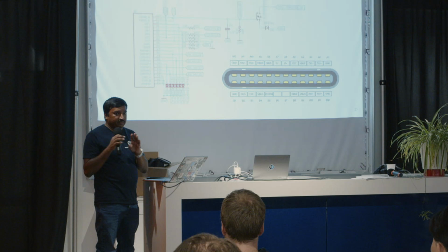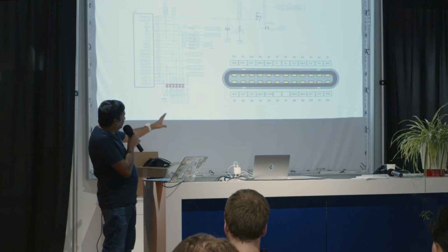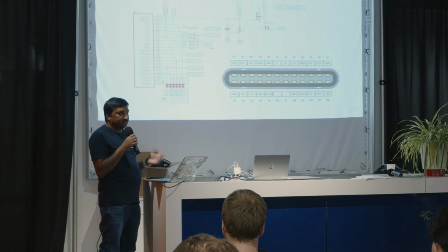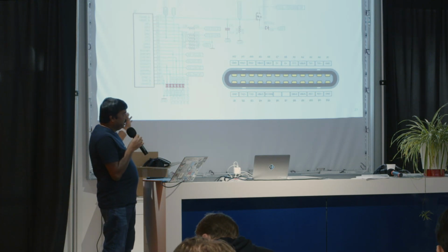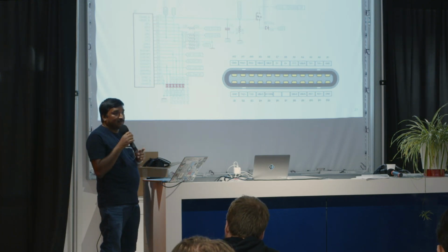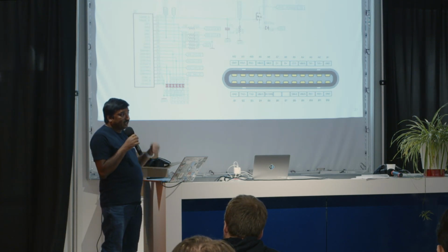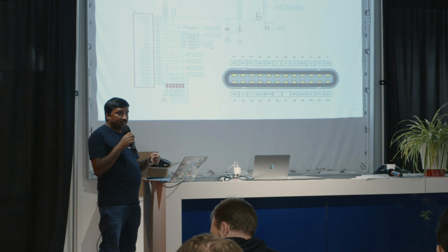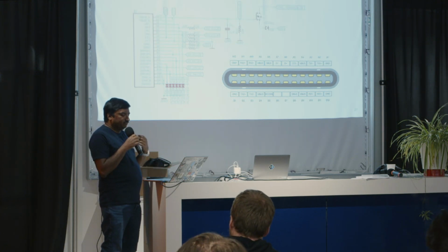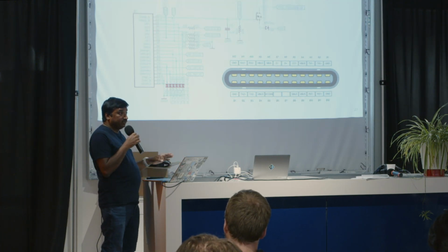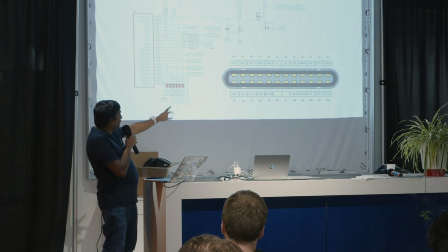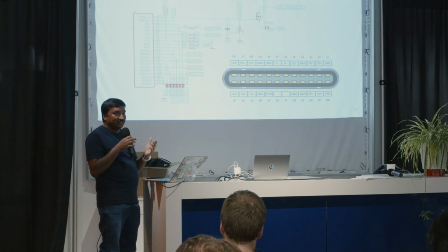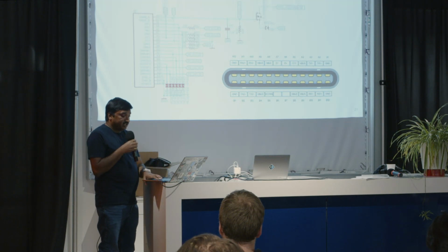But ours still works. The reason it still works is because USB has a hidden mode called debug accessory mode, and we did not find out about it until a little while ago. What that does is, there are these RX and TX pins, which are used as high-speed lines when you connect a DisplayPort monitor or, for example, PCIe over USB 3 and all those. Otherwise, they're never used. And the function of those is decided by these CC1 and CC2 lines, which some of you might recognize, but if you don't, I'll be happy to explain to you after the talk, because I'm already running out of time.